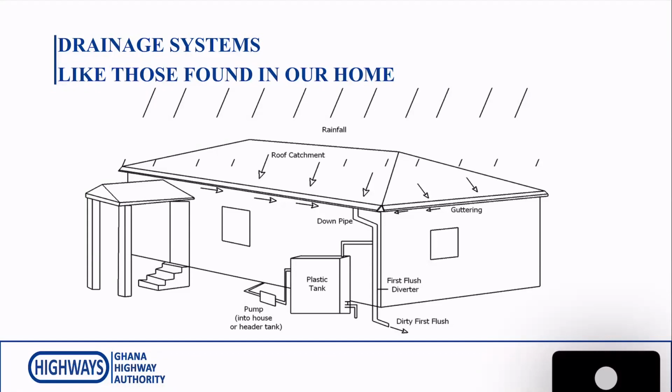Now, the road itself, if you are talking about paved roads, has a relatively impervious surface to keep water out of the base support. Options are actually available. And also to prevent surface softening and erosion. The surface of the road is normally sloped transversely, so the water runs off to the edges of the pavement and the shoulder, where you have side ditches that collect this water and convey it to a discharge point, like a convenient cross drain or adjacent stream bed.